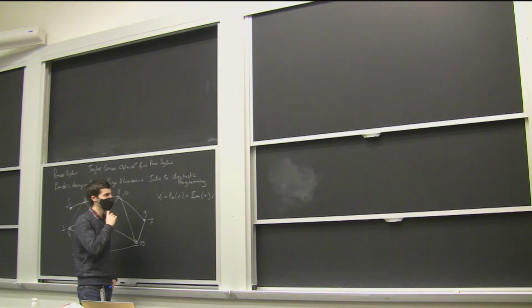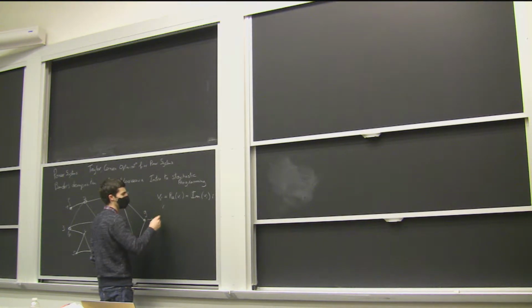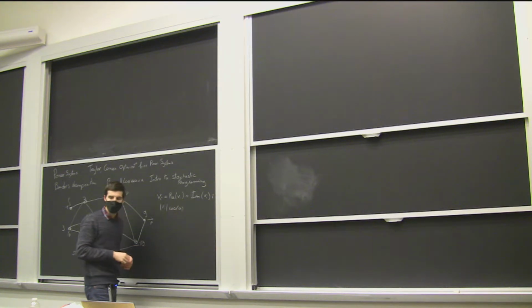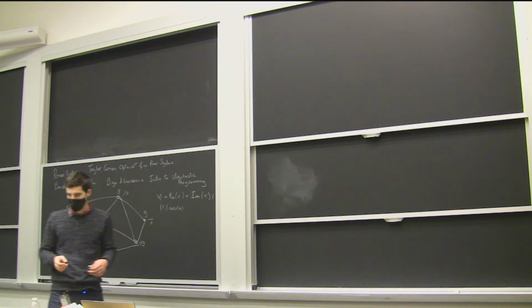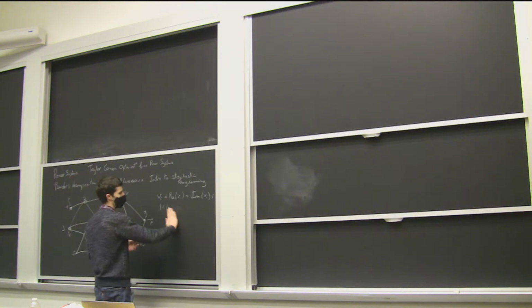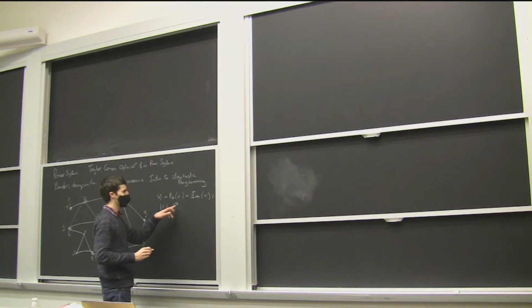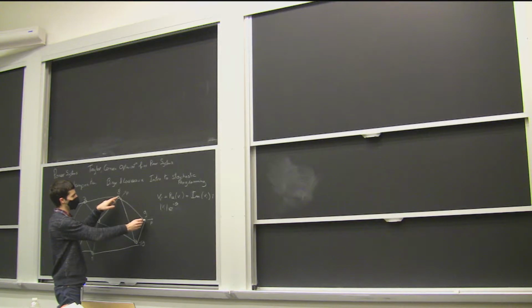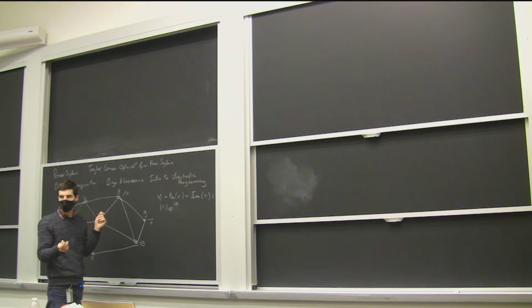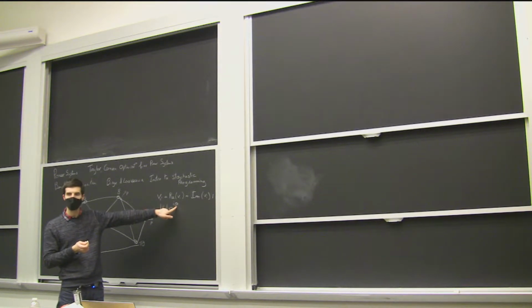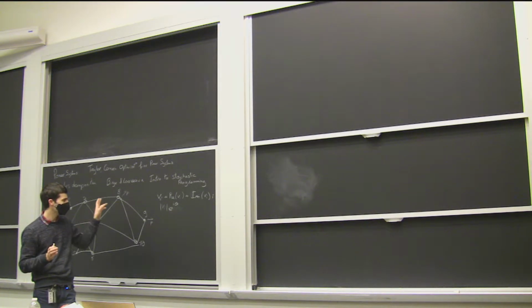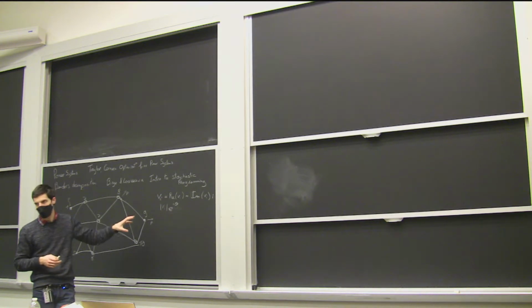In electronics, what they like to do, instead of saying that this is some alternating current of intensity Vi and then of some cosine, is to use the phase description. They represent the voltage as a complex number, and theta is the phase of the voltage. Whenever you have two tensions that have the same frequency but a different phase, you can see it with this different angle. And when you have nodes with different phase, this will need to be taken into account when you transfer electricity from one node to the other.